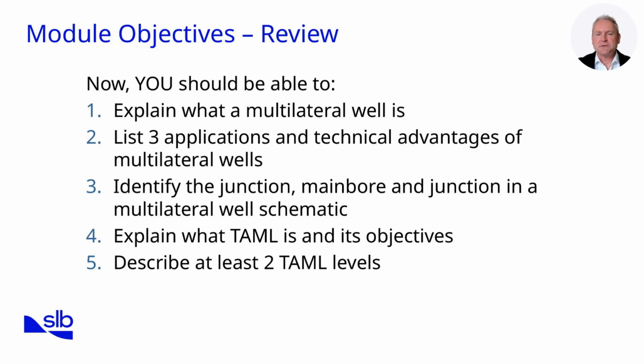Let's revisit the objectives of this submodule. We set out to deepen our understanding of the TAML classification system and the features that distinguish each level. First, we described the 6 levels in detail. We saw how Level 1 offers simplicity and low cost but minimal control, while Level 6 provides full hydraulic isolation and intervention capability at the highest cost and complexity.